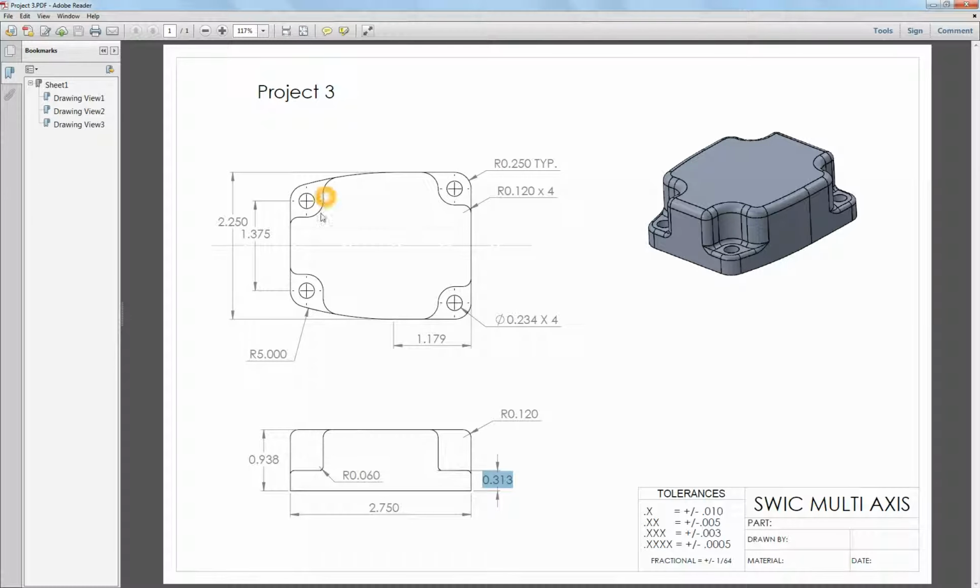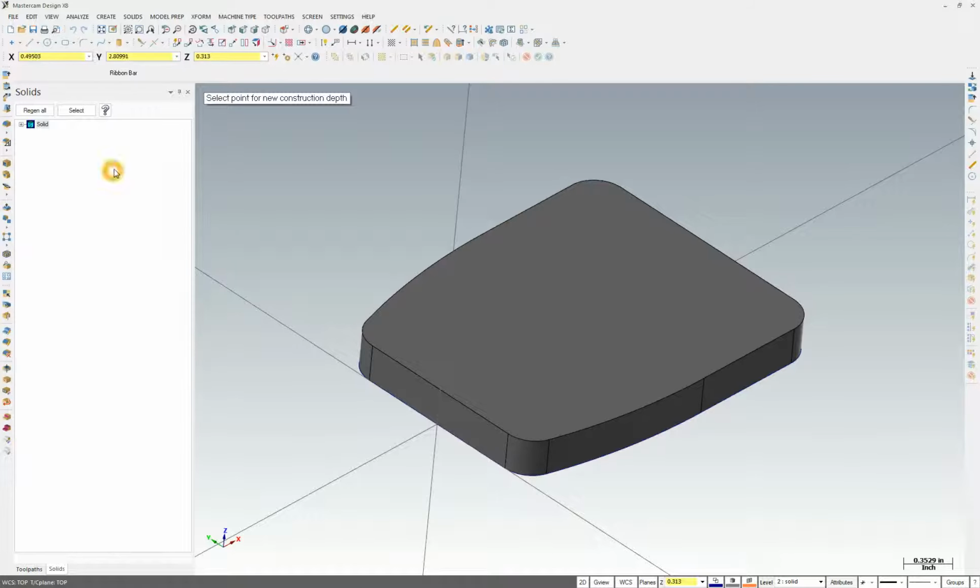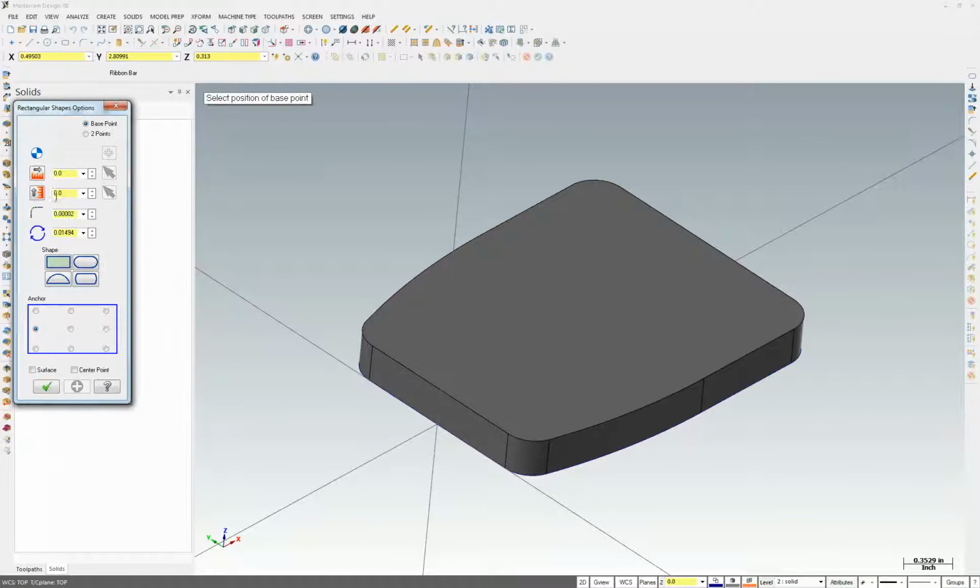Now, in order to get these fillets to go in here, we actually need to draw just a simple 1/2 by 1/2 inch square that represents this vertical line and this horizontal line. And to do that, we're going to use our rectangular shape, and we're going to lock in our values. 0.5 here, lock this one at 0.5 here. Make sure we zero this stuff out, because if not, that will bite you. It'll mess up your file, and you'll probably end up starting all over.